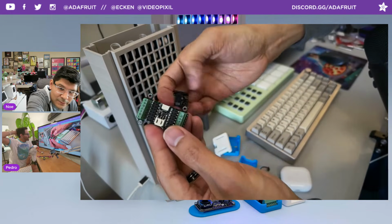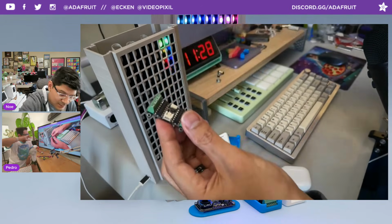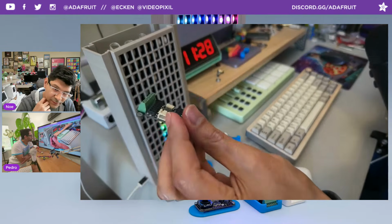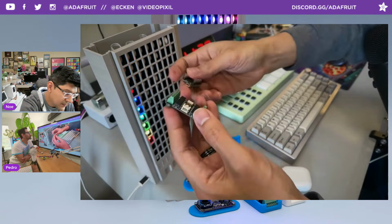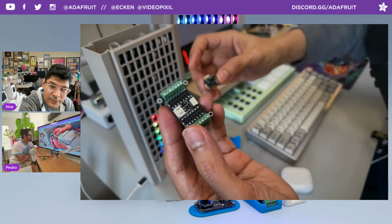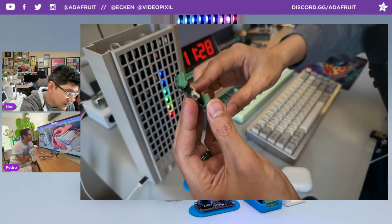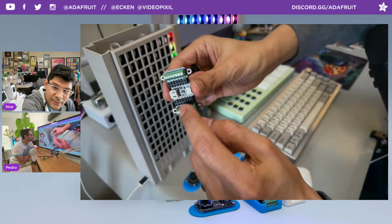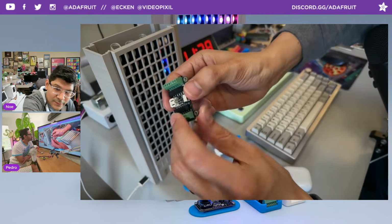And so Lamar was able to fit some onboard LiPo battery charging. So you have a JST port for battery. There's no on-off switch here, so if you do plug in a battery, you can't turn it off unless you manually disconnect the battery. But you do have some LEDs there to tell you when the battery's charged and when it's charging. And I think that's about it. And it has two sets of surface-mounted short profile headers.